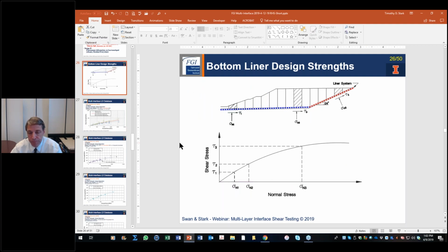Okay. So this is Marisa Vander Weisduzen, and she asks, when you have an earth embankment acting as a buttress on the toe, would you use a peak or residual on that toe, for example, maybe a three horizontal to one vertical slope. Okay, so the question is, if I build a buttress here with my cursor out here on the toe and bring it down to the ground, should you use peak underneath the buttress or residual?